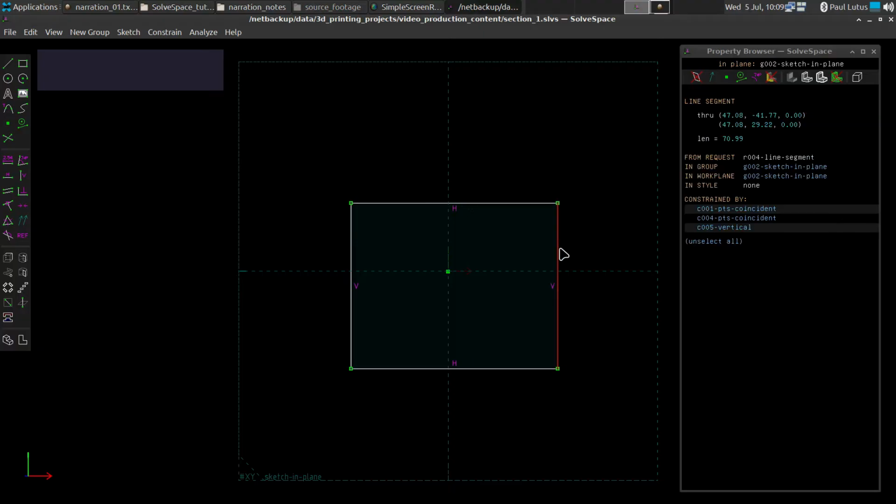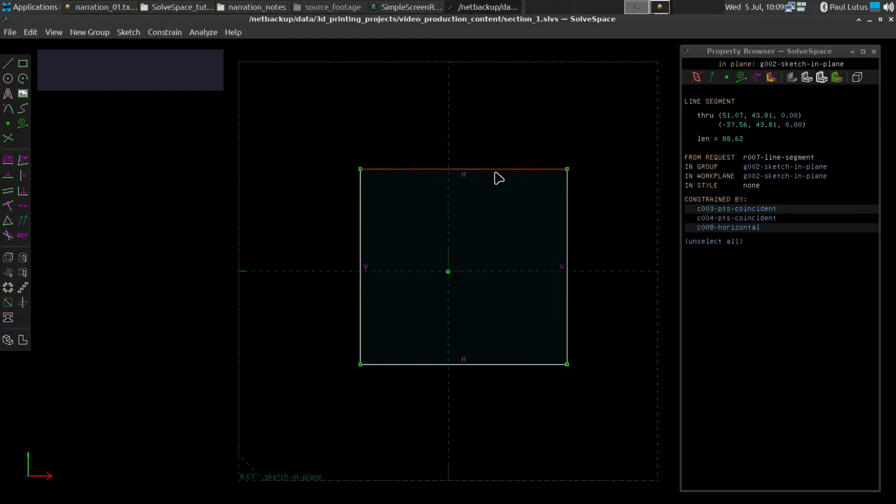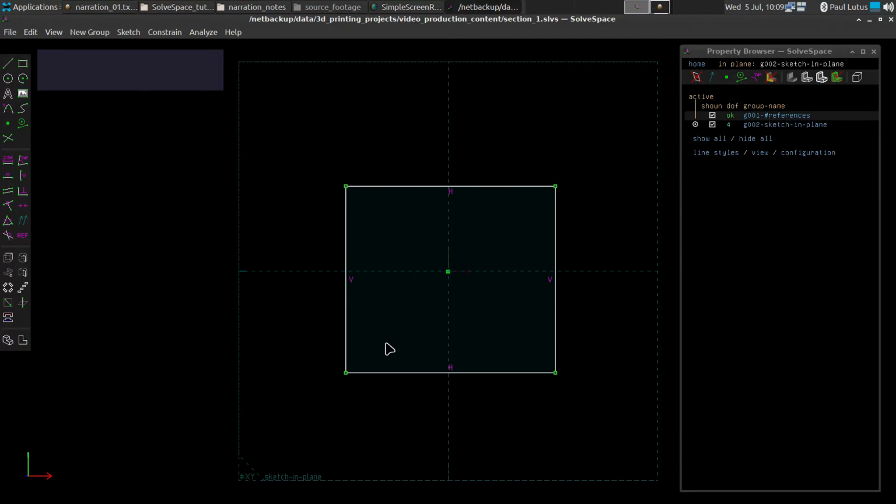At the moment, you can do pretty much anything you want. You can control this and move it around, obviously not a very useful drawing if it doesn't have any definitions within it. And so the constraint process is how you turn a 2D drawing into something reliable and consistent. And you always want the DOF to be 0 as the ultimate goal.